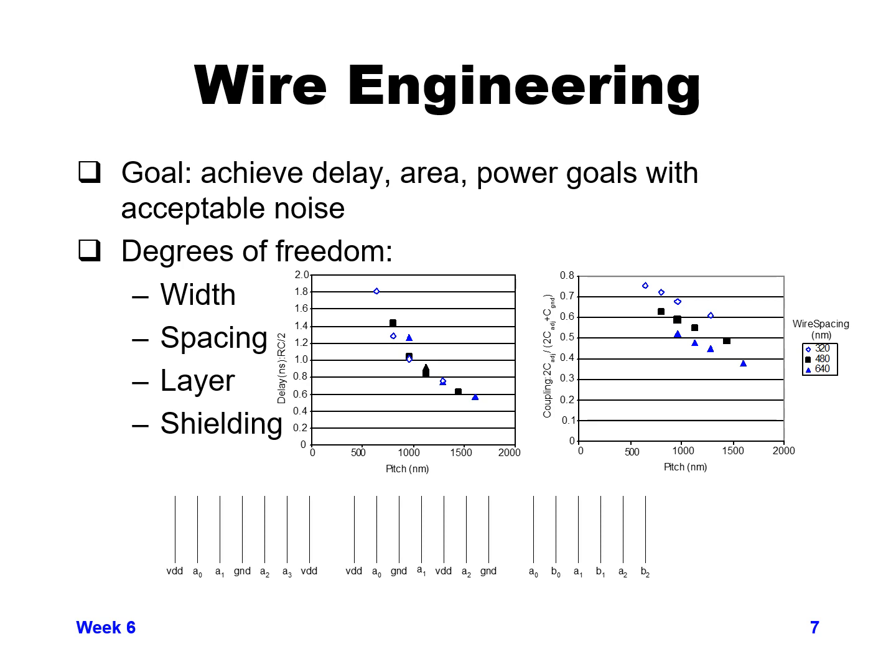For example, if you know the signals A and signals B never switch at the same time as each other, and so A is always going to be stable when B is switching, and vice versa. This will help as far as timing goes, because you know that your A signal, when it switches, is never going to be slowed down by B trying to switch in the opposite direction.